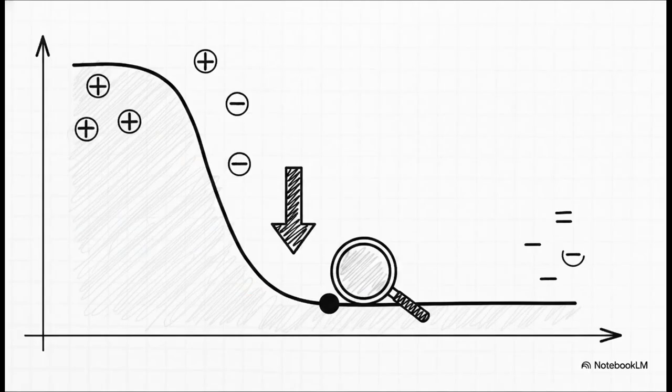To boil the rules of that graph down really clearly, our device hits maximum capacitance during the accumulation phase, it hits its minimum capacitance during the inversion phase, and right in the middle, during depletion, we see this rapid transition. The exact point where it levels off into inversion, that is governed by our threshold voltage. The big takeaway here is that manipulating the gate voltage dictates the electrical output in highly predictable, mathematically strict ways. It's a beautifully controlled system.